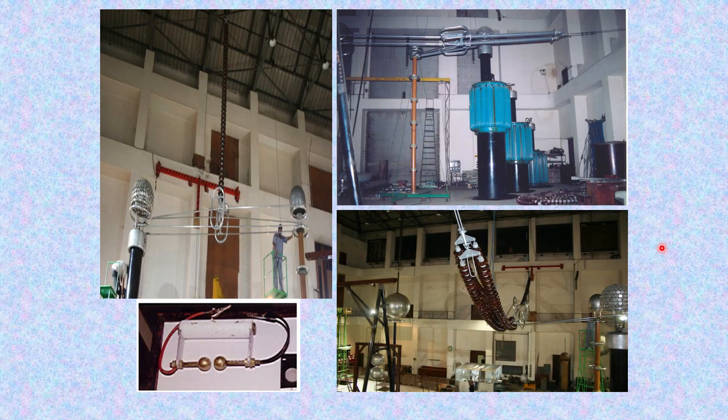These are all the mounting arrangements for various configurations. This is the sphere gap arrangement, a small sphere gap of 2 centimeter diameter, and the spacing of the gap could be 4 millimeter in this case. There is standard breakdown voltage information available in the standard. This is measured as per the breakdown, then converted to laboratory conditions, standard temperature and pressure, and it will be connected across each disc.